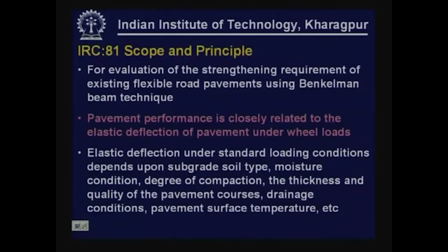The scope of these guidelines is evaluation of the strengthening requirement of existing flexible road pavements using the Benkelman beam technique. So, this is meant for flexible road pavements and is also meant for the Benkelman beam pavement evaluation technique. Pavement performance is closely related to the elastic deflection. It is believed that pavement performance is closely related to the elastic deflection that the pavement undergoes when it is subjected to a standard load.